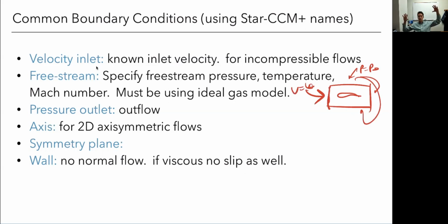And then it's just going to let that drive the solution. I'm going to use my finite difference or finite volume solution. And then I'd have another condition here, which is like, say, a wall, which says the normal component of the velocity has to be 0, for example. Or if it's no slip, then v at the wall is 0, right? So those are the two different kinds, whether it's inviscid or viscous. So once I specify all these boundary conditions, then I just iterate until this solves.